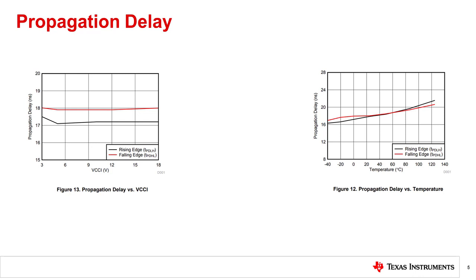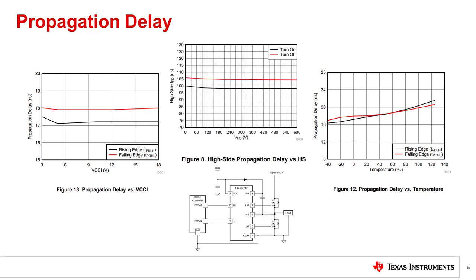Isolated drivers are not meaningfully affected by the application of high voltage across the isolation barrier, since the isolating element does not see a significant change in physical properties, and therefore the high-frequency transmission characteristics are not disturbed. Compare this to applying high voltage to the high side channel of a non-isolated half-bridge driver, which can impact the propagation delay by affecting the level-shifting transistor capacitance.